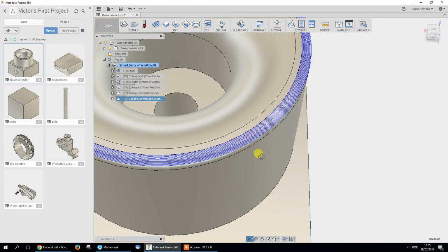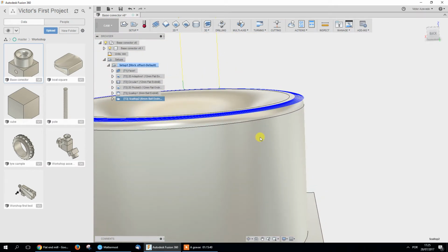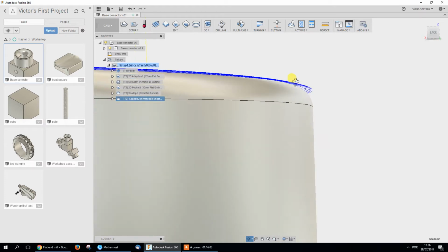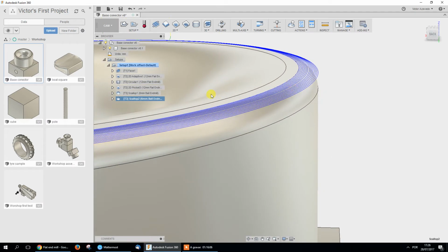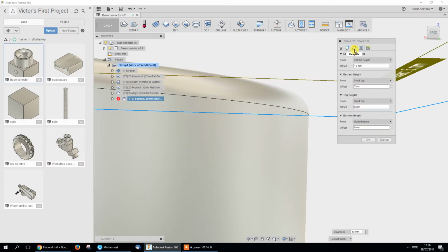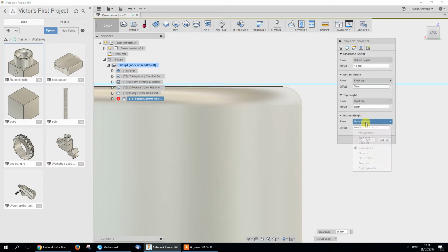That's it. And also, it's from inside out or from outside inside. I don't care in this case. I can select either way. Yes. In this case. Might be useful on others. This 0.1. This might not give you a really good finish because it doesn't go all the way down. You might need to define the height a little bit lower for the bottom.